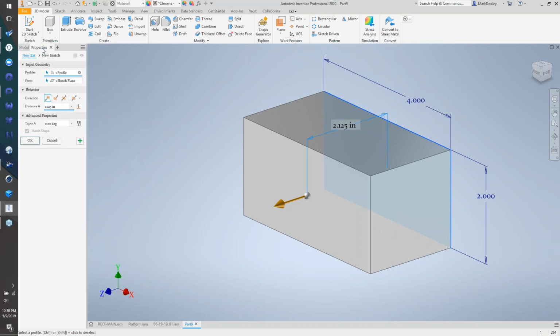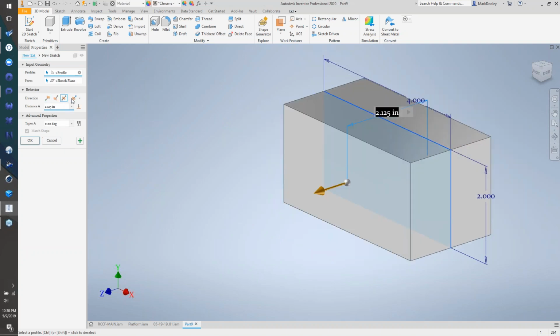So if I want to drag this over here and put it right in the side, so I've got more graphical real estate, I've got that option. And so direction 1, flip to direction 2, symmetrical, asymmetrical, all the options are still here. So you've got the little 3 bars here for the advanced settings menu, and so you can keep the sketch visibility on. You can hide your presets, so that's default.